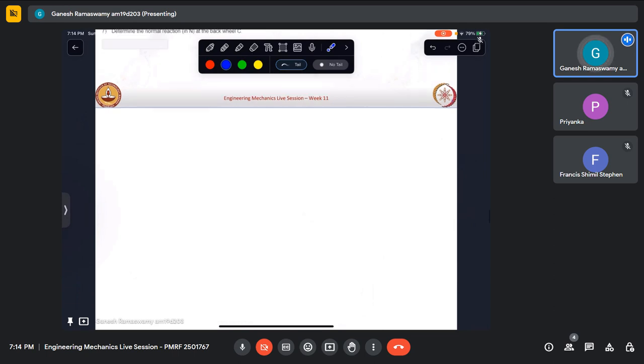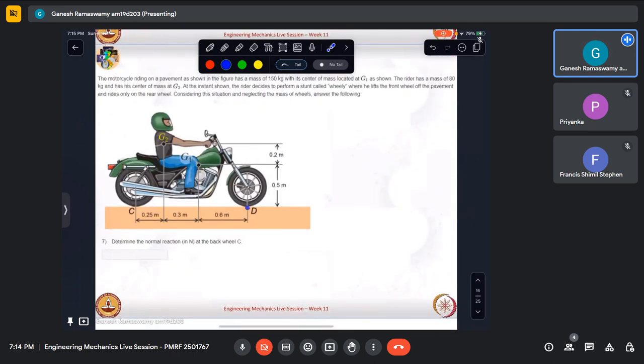Now at this instant when it has left the contact here, it is undergoing rectilinear translation. Just that this has lost contact now. So the entire thing has to be mobilized by two components. One is the normal component and one that is the friction acting at this point, which would have to balance mass and whatever the kinetic quantities are. It is undergoing only rectilinear translation with two masses separated.